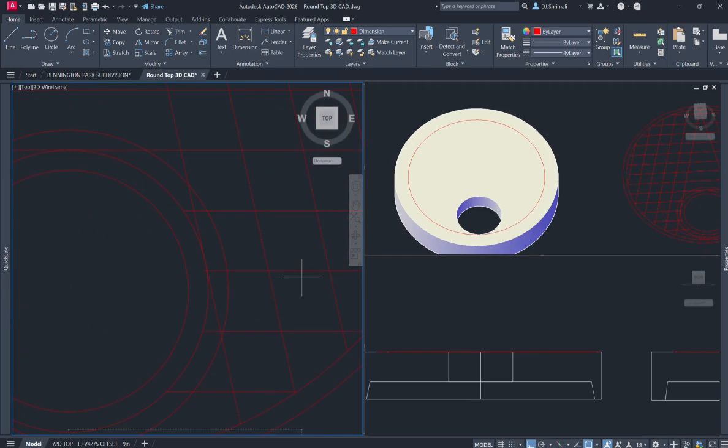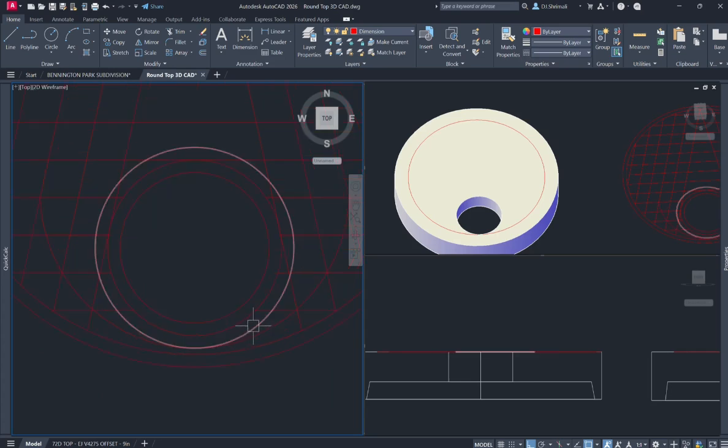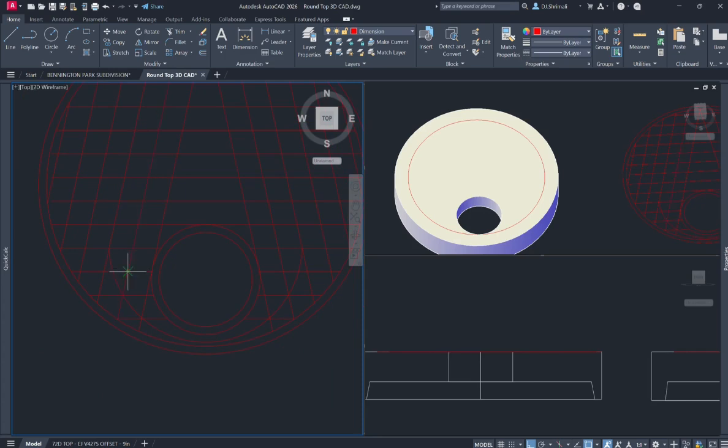So for that, whatever the opening is, you always have to put a diagonal rebar. So here I am putting that, the band bar and the diagonal rebar, since it's a curved top. If you have a space to put like 4 diagonal bars, just like I'm drawing the 2 diagonal bars, then you will put the 2 diagonal bars. Okay, and yeah, like that.